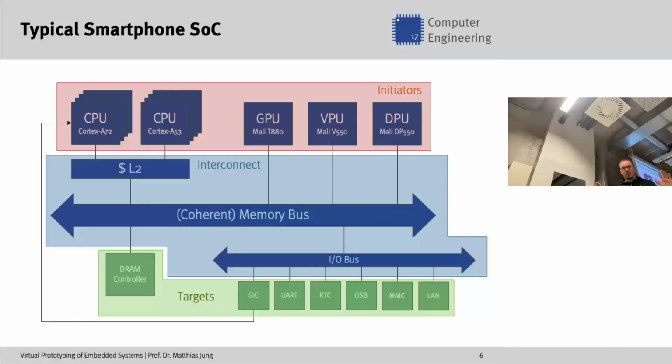And this is the basic semantic that we use in transaction level modeling. So we will have modules that are initiators, we will have modules that are interconnects, and we will have models that are targets. And an interconnect is an initiator and a target at the same time, actually. Because it receives something as a target, like this cache.